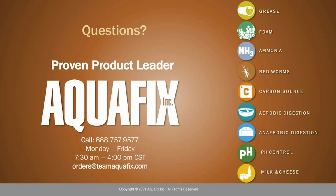I find in a lot of digesters that are completely mixed, you aren't likely to have many issues with quat because your solids holding time isn't very long, and a lot of the quats are inactivated by sticking to acid-producing bacteria and facultative bacteria, which means they don't make as much contact with the methanogens, limiting the amount of problems they have.